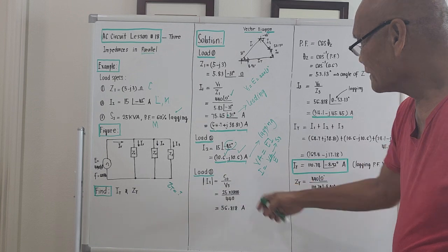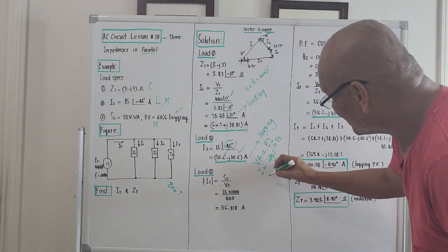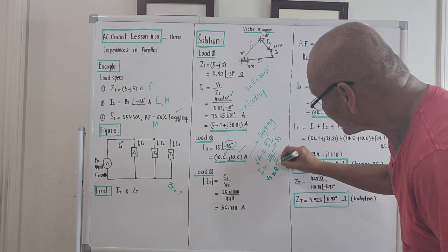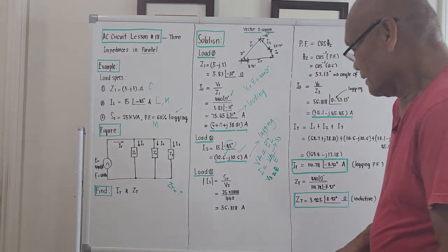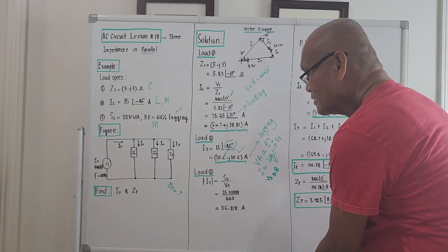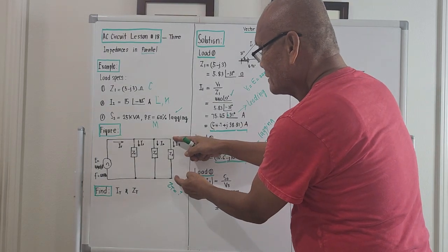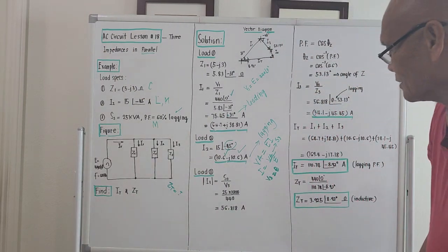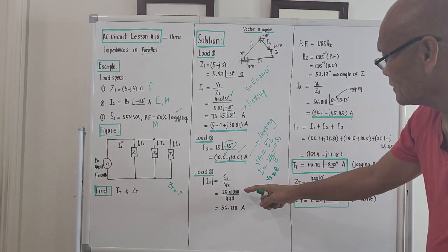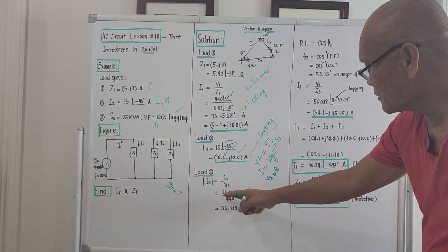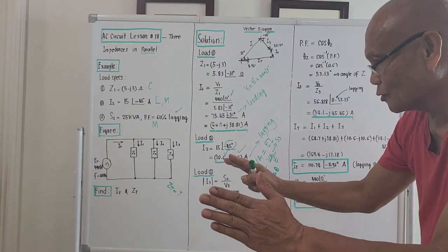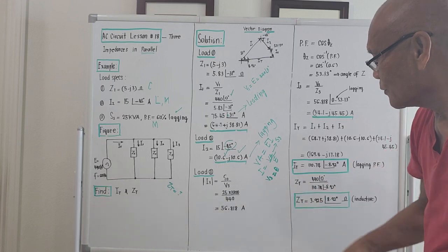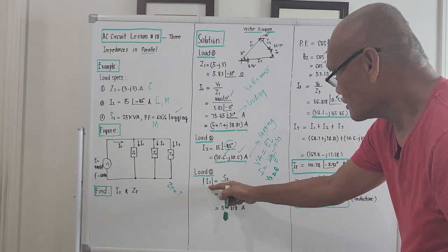So this will now be equal to S3 over V3, and also V3 is equal to E, the source voltage, right? V3 is the voltage across this, equal to the source voltage because the connection is parallel. So converting this, because this is kVA, right? For it to become volt ampere, we multiply that by 1000 over 1440. This is just the absolute value.